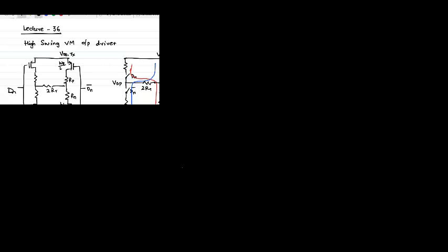On the lower side that should be equal to RNMOS plus R poly resistance. It should satisfy that property to have a termination on either side. Now if your R poly is much greater than R MOS,